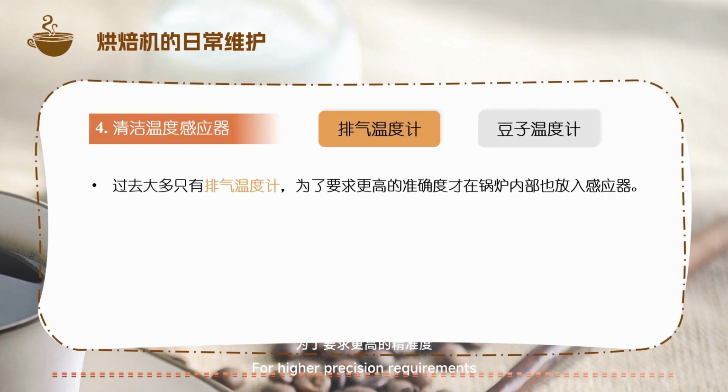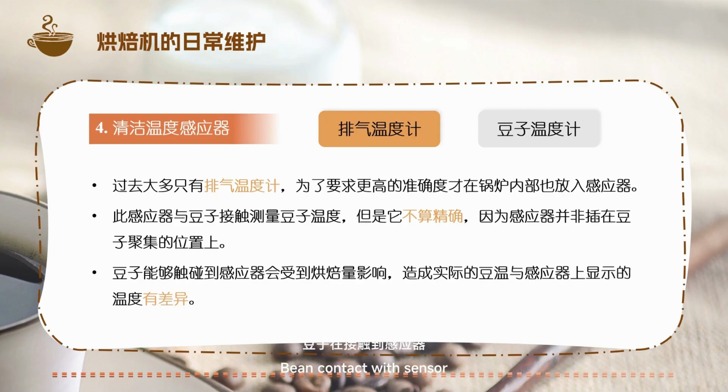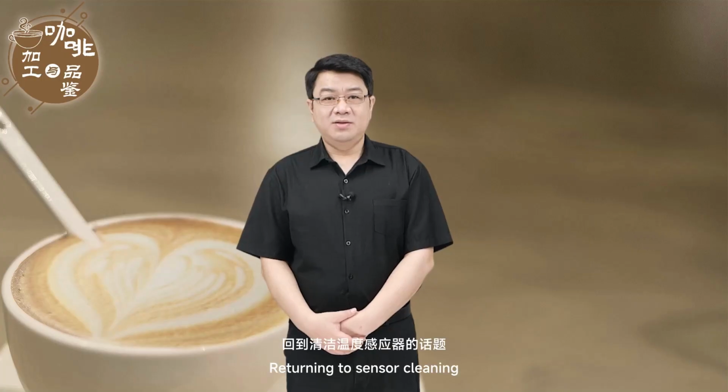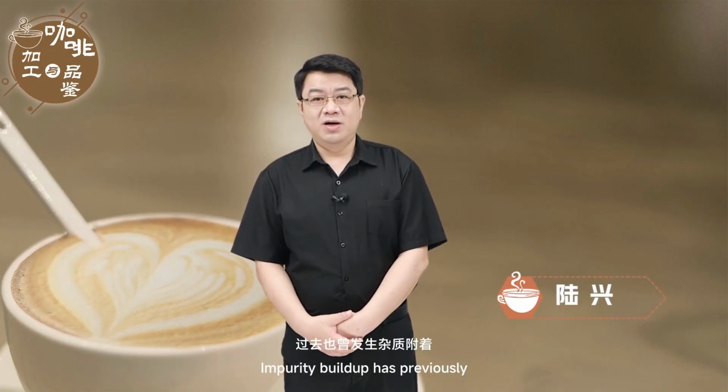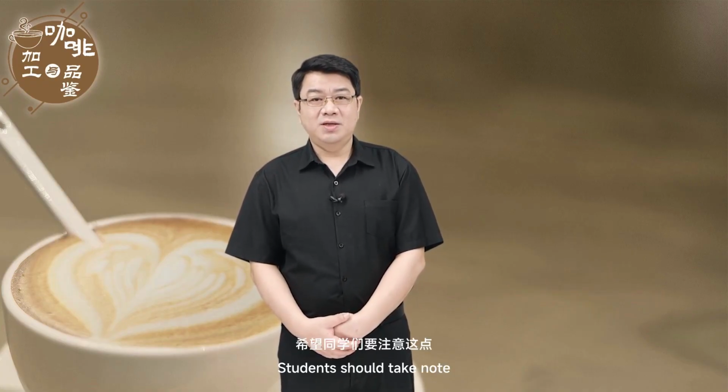For higher precision requirements, sensors were added inside the drum. This sensor contacts beans, measuring bean temperature, but isn't perfectly accurate because it's not placed where beans concentrate. Bean contact with sensor varies with roasting volume, causing actual bean temp to differ from displayed readings. Returning to sensor cleaning, impurity buildup has previously caused sensors to become permanently stuck. Students should take note.